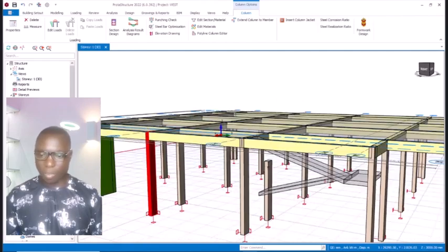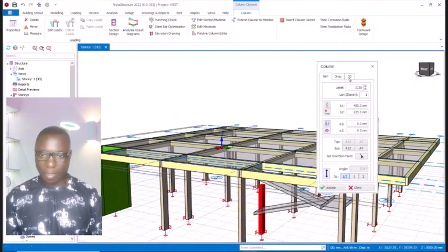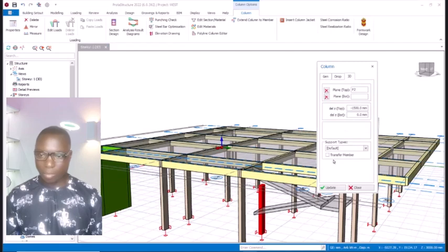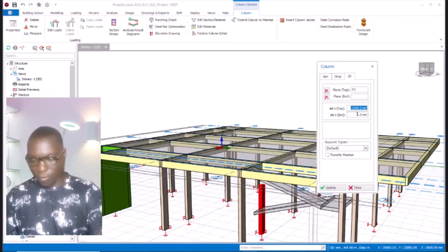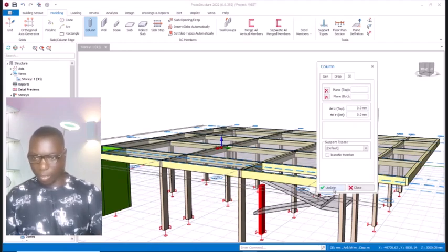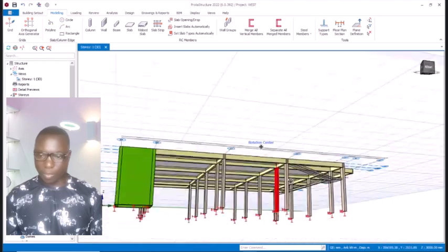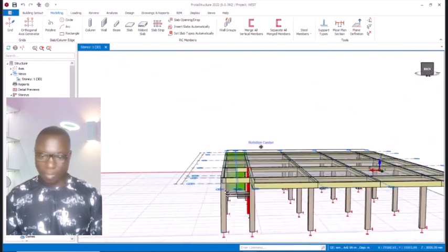Let me see what happens here. I'll right click there again, click on the properties, onto the 3D. So we have here to be 0. Instead of minus 1500, you key in 0 right there. Click on the update. Okay, it is not correcting. Then remove this plane right here and then click on the update. You see it goes up successfully. I closed. You can see now we have our column in place.